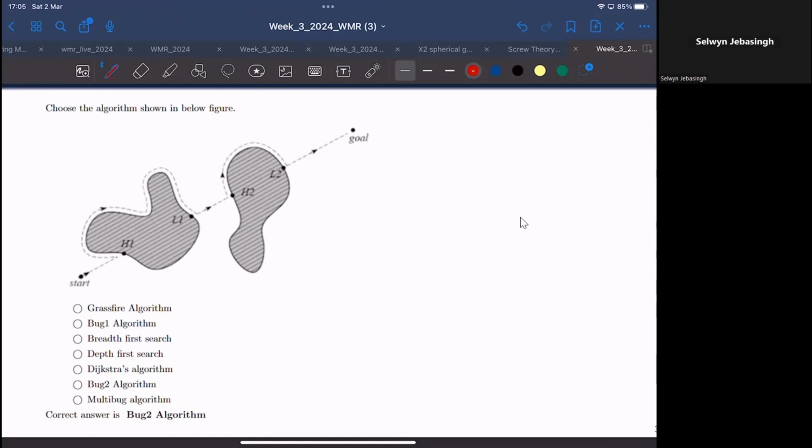But why do you really have to multiply it with 9.81? Because if you can see the solution range, mass is given as 5 kilograms. So the moment of inertia would be mk square, right? Radius of gyration is also given. Yes, sir. But the mass is given in kg, sir, and we are not converting it into Newton. Why do you have to convert it into Newton? Because they are asking for Newton meter, sir. They are asking the torque.